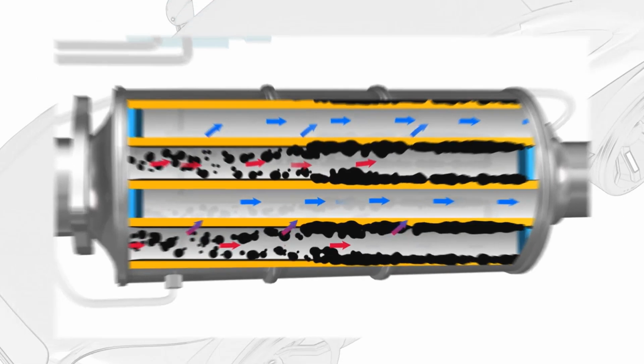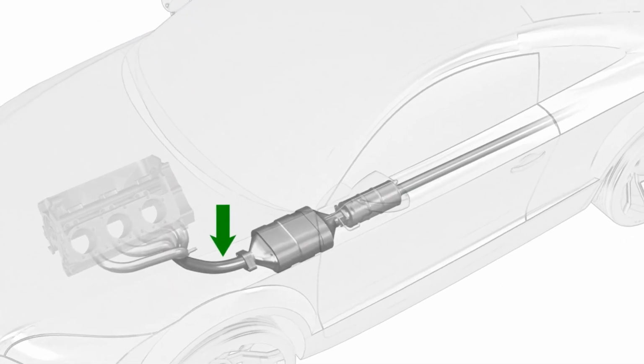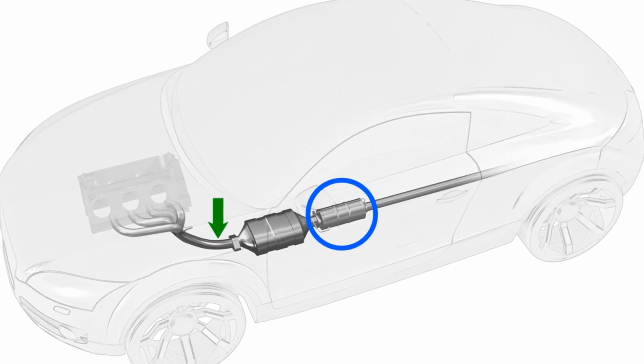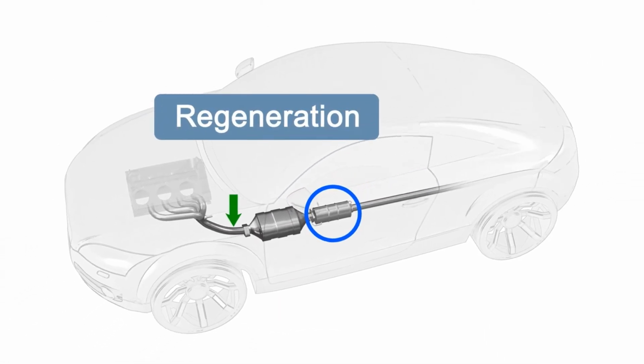The DPF is located before or after the NOx catalyst. A major feature of the DPF is its ability for regeneration. Regeneration is very important since an overfilled DPF can damage or cause poor running of the engine due to excessive exhaust back pressure. The material trapped in the filter is in the most part carbon particles with some absorbed hydrocarbons.